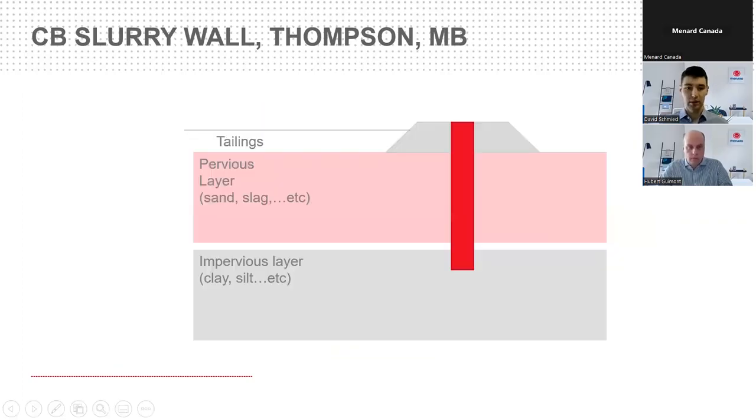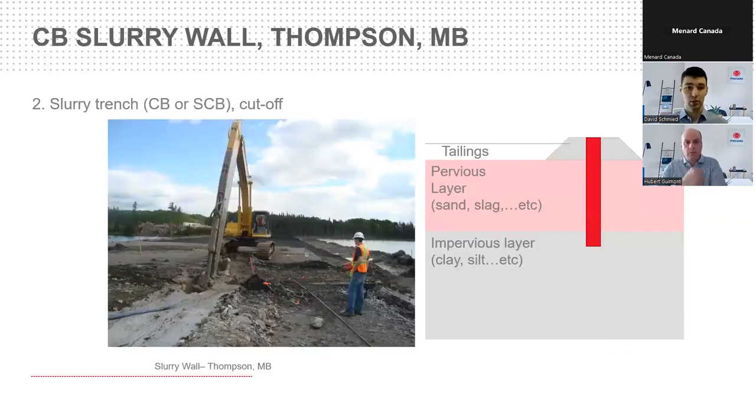Secondly, then we came in with the cutoff wall. So once the area was compacted, we came in and did a cement bentonite cutoff wall. As you can see here, the excavator is digging along, starting a new panel. This is the semi-cured panel from probably the night before. And you can see the slurry line, and that would be pumping slurry the entire time he's excavating.